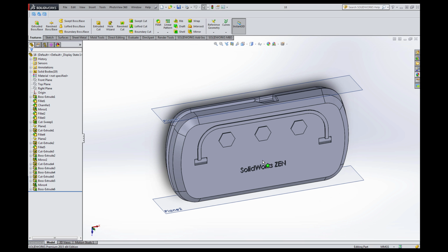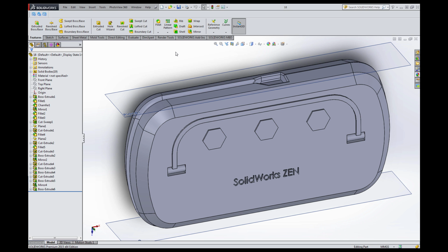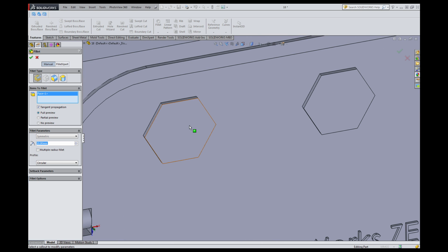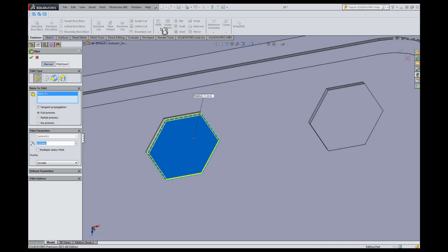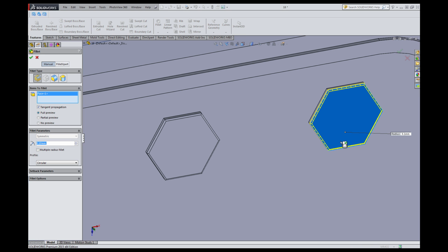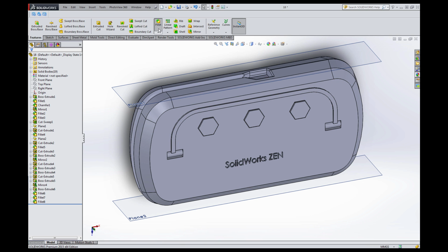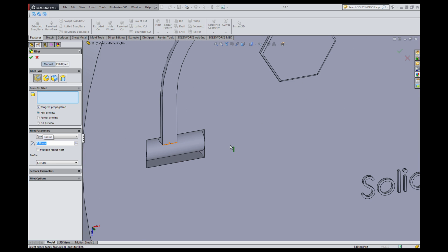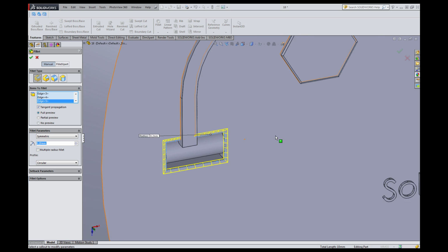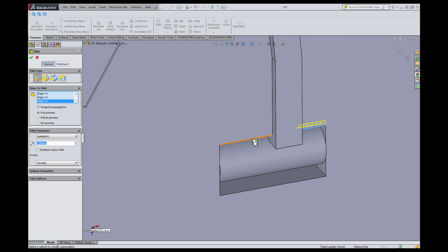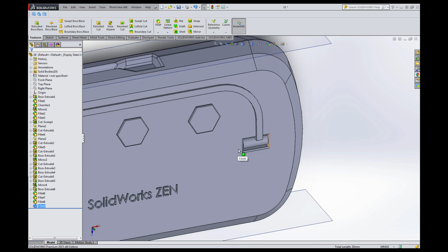Now I will embellish a bit some parts using fillet option. So I'm going to fillet and select these edges and put 0.1 millimeter and confirm. Now I'm going to repeat this step for other buttons. Okay, confirm and fillet again and confirm. Okay, now fillet again, but this time 0.2 millimeters radius for those edges right, oh sorry, those edges right here.